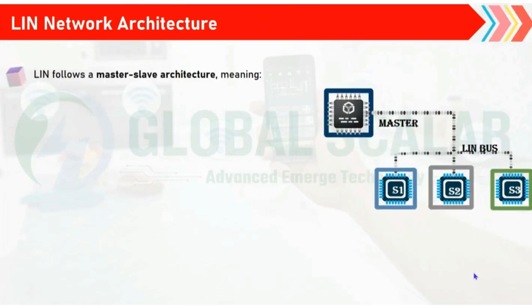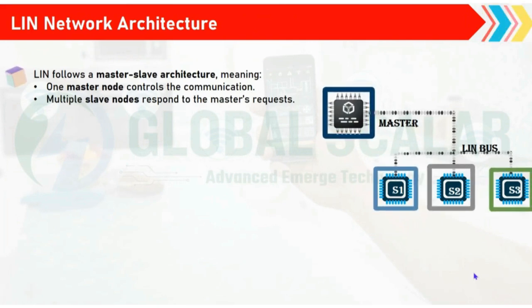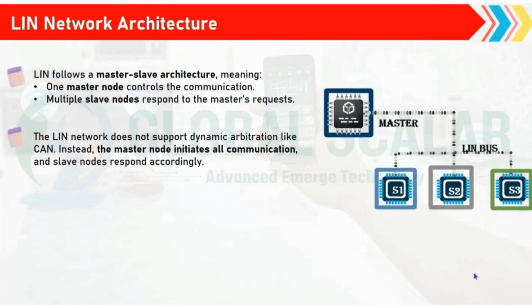This master and slave architecture follows one master node controlling the communication, with multiple slave nodes responding to the master's requests. The LIN network doesn't support dynamic arbitration like the CAN protocol. Instead, the master node initiates all the communication and slave nodes respond accordingly.